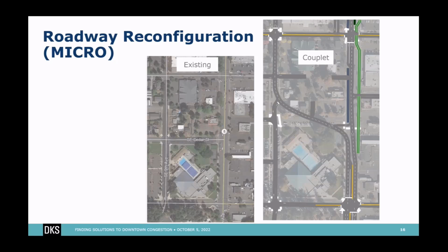You'll also notice on the side, we started to see what the possibilities might be for all that extra space on 10th Avenue. So in this example, we're showing a cycle track on the right-hand side of 10th Avenue in green. And that gave us the opportunity to test what the impact of special phasing just for those bike movements might do on the signals and if we could accommodate that.